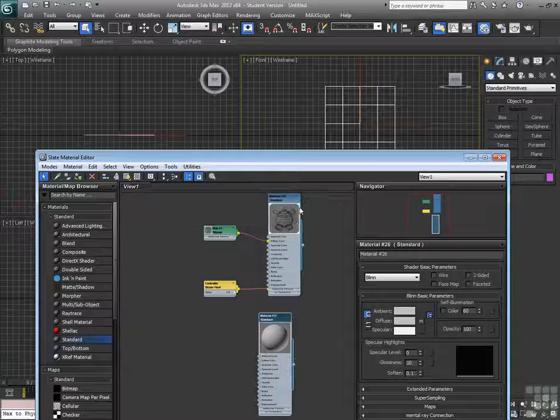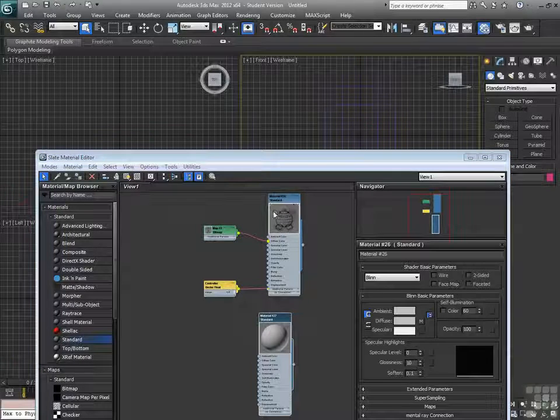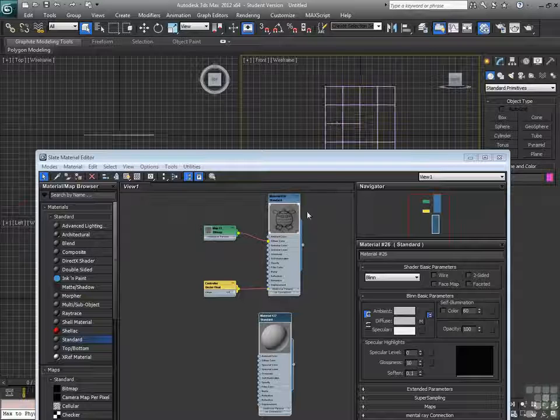The corners that show up in the materials preview there kind of clue me in as to whether or not this material exists in my scene or doesn't. So this one does, and it's on my selected object. If I were to deselect that object, you see those little corner icons turn gray. There's still corner icons there, which means the material exists in the scene. It's just not on the selected object. So if I reselect that object, those icons turn solid white.